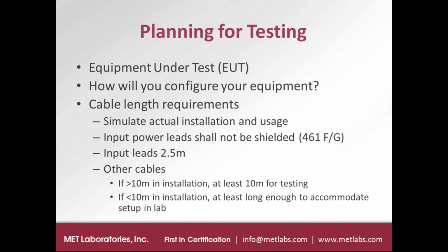However, they want you to also follow certain rules that are laid out in the standard. So input leads need to be exactly between 2 and 2.5 meters. So you're often shortening input leads before we start testing. And then all other external cables, if those cables would be greater than 10 meters in the installation, then at least 10 meters are required to be included during testing.